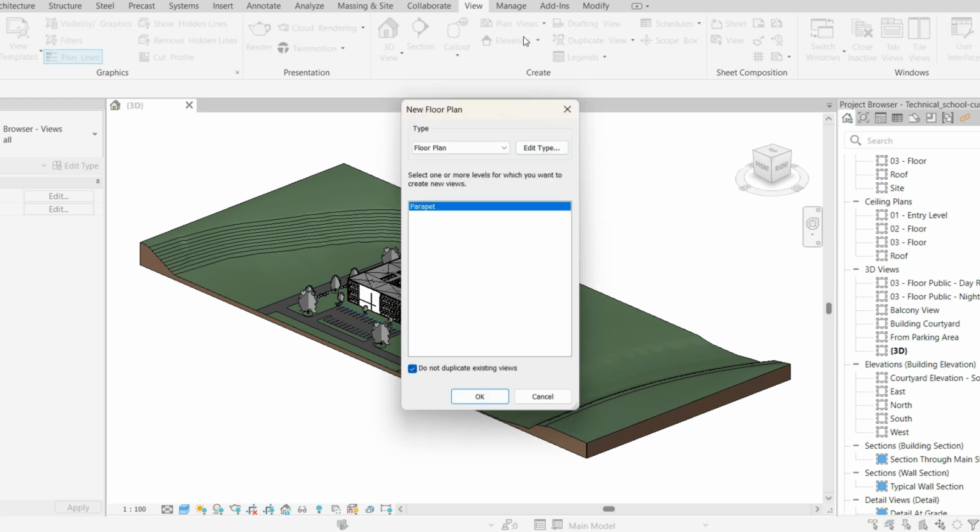Creating a floor plan in Revit involves several key steps, which can be broken down into the following process. In the project browser, under Views, right-click Elevations and choose View Properties to define the levels for your building, e.g., Level 1, Level 2, etc. I am selecting Roof Plan now.